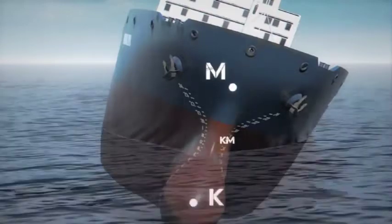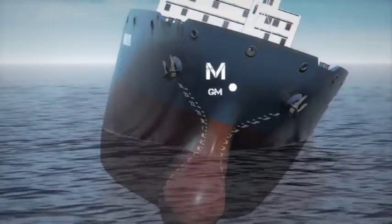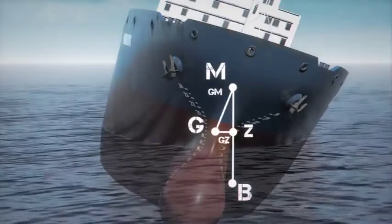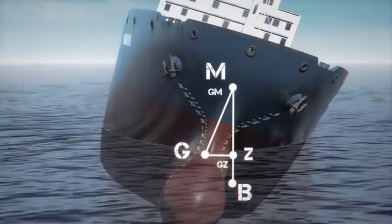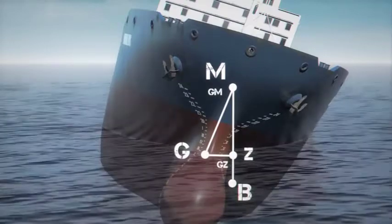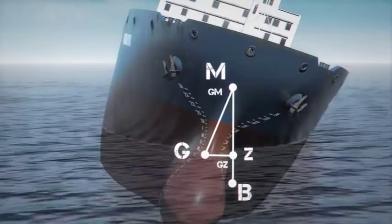KM is the vertical position of M, measured upward from the keel. Metacentric height, or GM, is the vertical distance between G and M. When we put these things together, we see the ship's stability triangle. This shows us that the larger the GM is, the longer the righting arm, or GZ, will be. The longer the righting arm is, the greater the force of the righting moment will be, and the ship will have a greater ability to right itself.